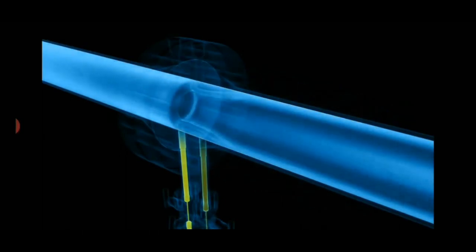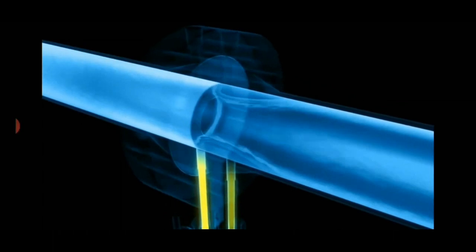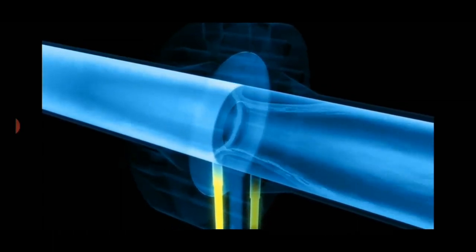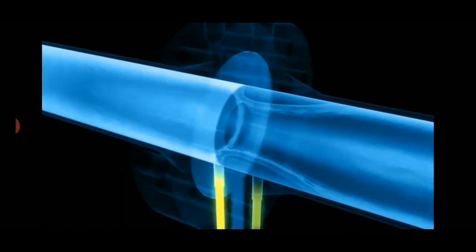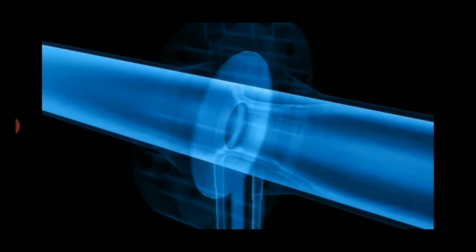As per Bernoulli's theorem, the speed of fluid and the flow rate are directly dependent upon each other. So we can easily find out the flow rate also using the differential pressure.